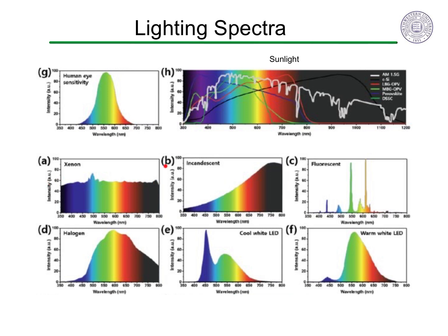The incandescent bulb is a hot filament that produces black body radiation. However, the typical incandescent bulb has peak intensity in the infrared and so produces a lot of heat and warm red-orange light. It has an equivalent temperature of 2700 Kelvin. Halogen incandescent lamps run hotter, around 3,000 to 4,000 Kelvin, and peak in the visible, which makes them somewhat more efficient.